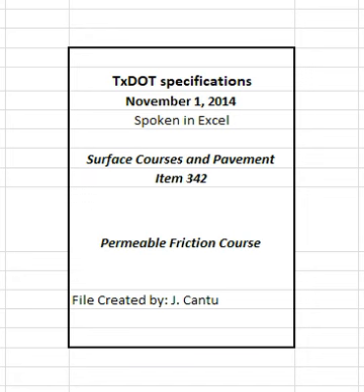4.4.2.1.3 Hamburg and Overlay Testing. Use an approved laboratory from the department's MPL to perform the Hamburg wheel test and provide results with the mixture design, or provide 10,000 g of the laboratory mixture and request that the department perform the Hamburg wheel test. Provide 25,000 g of the laboratory mixture and request that the department perform the overlay test. The engineer will be allowed 10 working days to provide the contractor with Hamburg wheel and overlay test results on the laboratory mixture design.